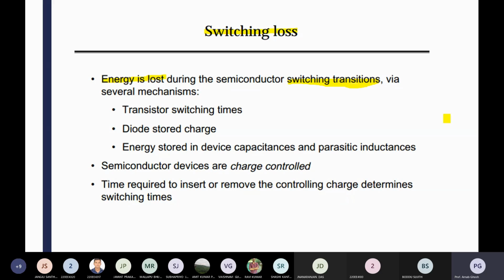So what will be the blocking voltage in the case of the passive switch? It will be a reverse voltage, the negative of your input voltage in the case of a buck converter. That amount of voltage appears across the diode, and initially there will be no current through that diode. That voltage is not enough to cause reverse breakdown of the diode, so it is applied directly but reverse breakdown does not occur.